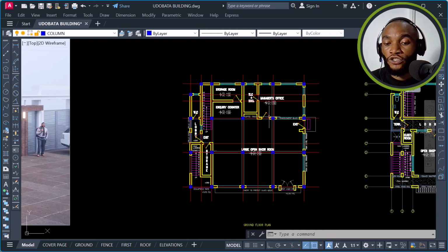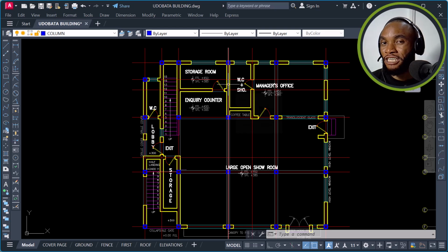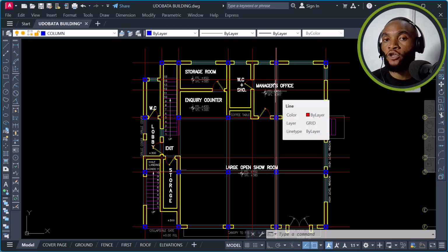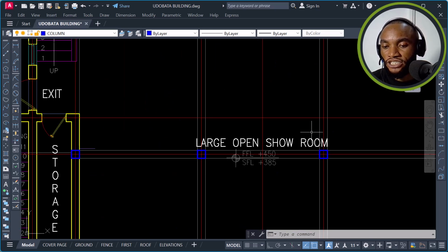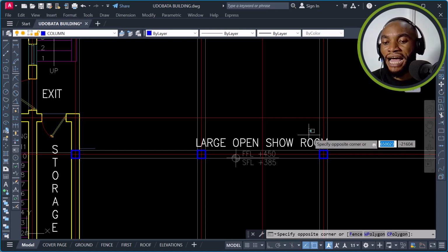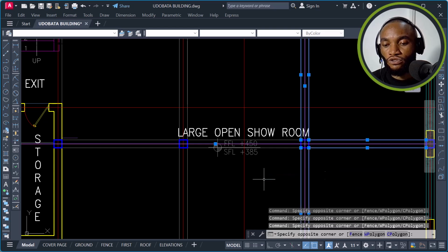Okay, that's fine. So with this now, let me just recap again. Column points or position depends solely on you as a structural engineer. You have to brainstorm, think about how to place your column points. Now, to help you on that, you have to look out for the strategic points where your major members are connected. For example, you can see that this joint now is a major point where these four beams are meeting: 1, 2, 3, and 4.